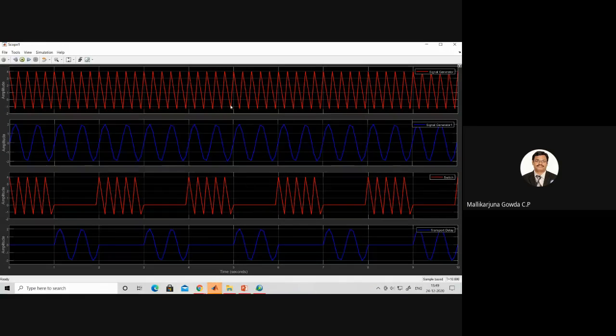The first point: I am displaying two message signals. This is my signal one, and this is my other signal. The first one is the sawtooth, the second one is the sine wave, and for the other two windows, I'm taking message signal one only at T1, T3, T5, T7. The second message signal I get at T2, T4, T6, T8, and so on.